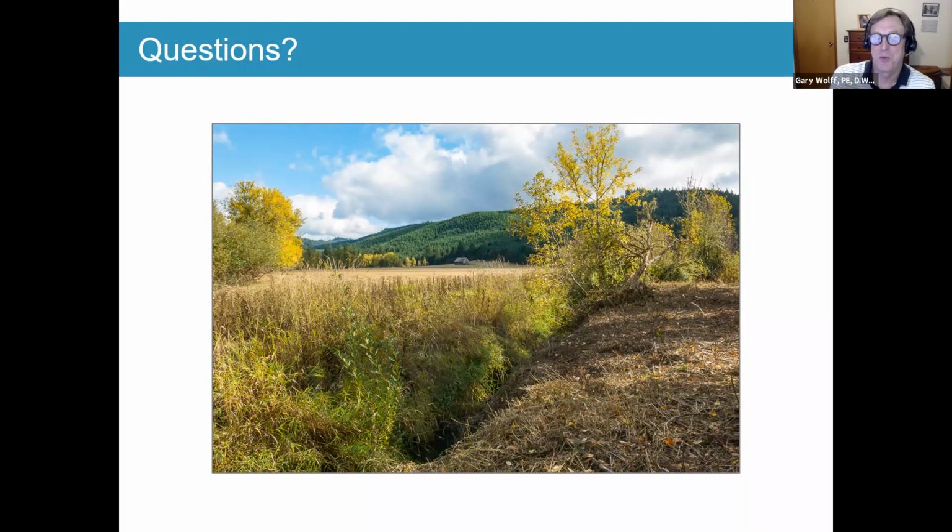First of all, I'm not too worried about low flow sedimentation for this particular stream. This is a very cohesive soil in the stream. There's not much bed load. And as you saw in the photographs, the existing bridges are actually scoured out underneath the bridges. There really isn't much of a sedimentation issue there.